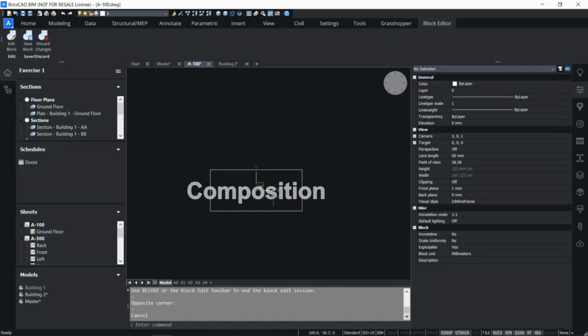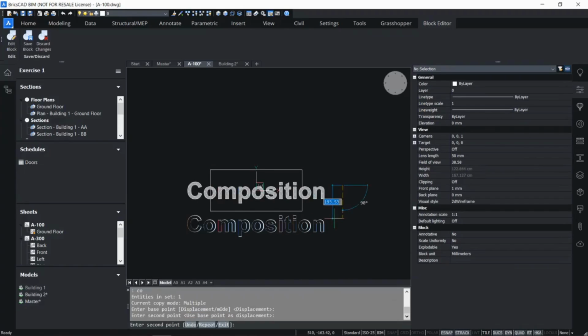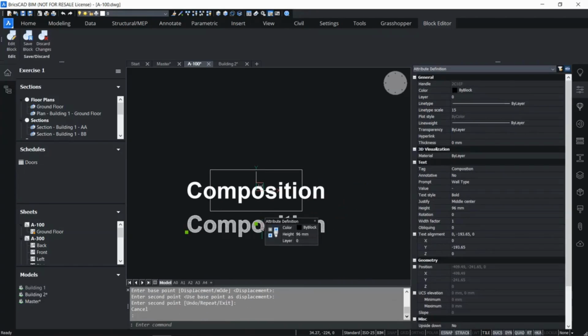And then underneath that, I want the thickness. So I copy the composition tag and its attribute, and I copy it along. These are actually attributes with a tag, and this tag is what will be represented in the real tag. So now I want the quantity, the thickness, and you specify it by typing in quantity/thickness. The syntax is always the property category name / the property name itself.